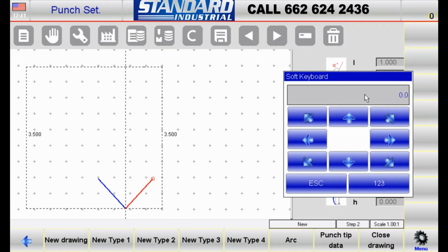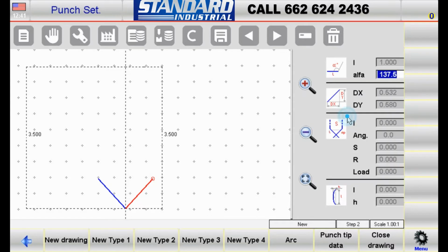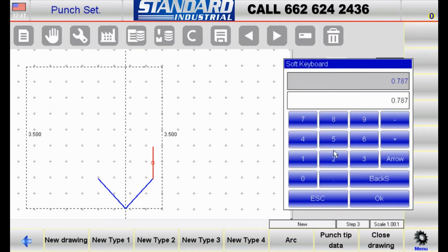When entering information about line directions, you have several options. You'll see that each of these arrows represents a fairly standard direction. In this case, we're going straight up, so we can hit the up arrow and it'll automatically insert a line direction for us. Now that it understands which direction we're going with the line, it wants to know again, well, what is the length of this line? And in this case, this side is 2.75 inches.